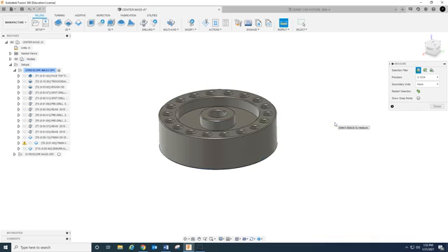So when you've got different material, when I said I checked a couple different lengths and they were all over the place, one of them I picked up was 1.5 inches. The other one was 1 5/8 inches. So what I'm going to do is go to worst case scenario there. I'm going to go to 1 5/8 inches, meaning that I had an 1/8 inch of more material to cut off. And this is because I don't know what piece of material each student's going to pick up.